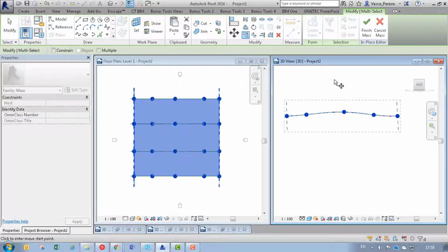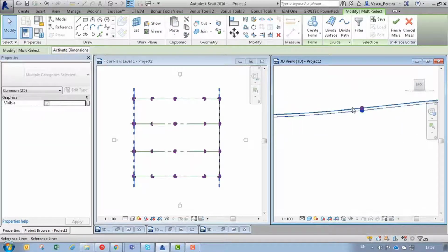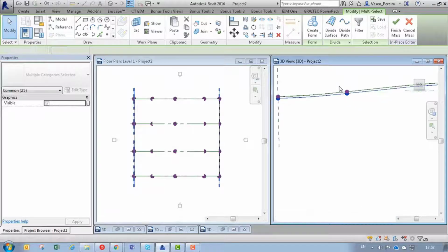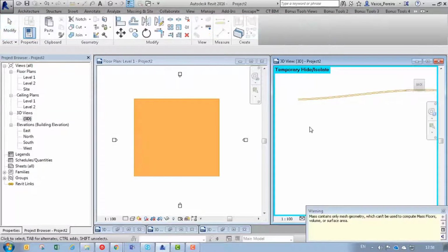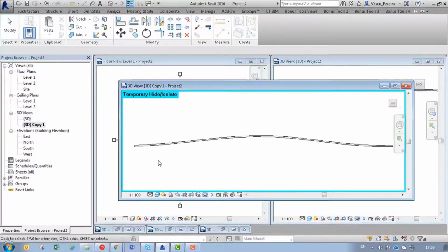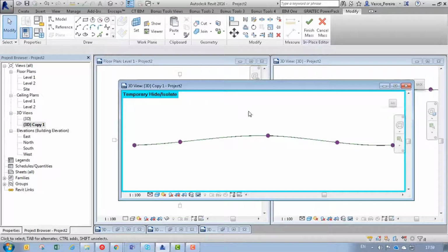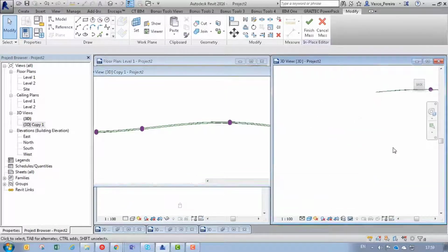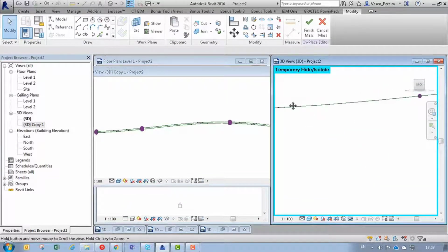So what we're going to do is select everything again, copy, and I'm going to drag it down for 150. There is one problem, is that these are so close. Sometimes I want to select just the bottom ones or the top ones, so I will hide these ones. So I'm going to finish form and duplicate the view. So now when I edit this view, I have this still hidden, and I can reset the height. So here I hid the bottom ones.